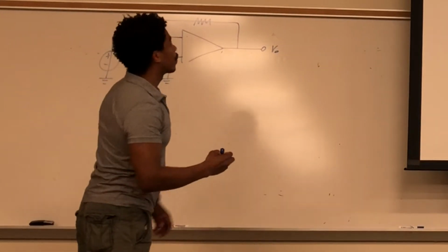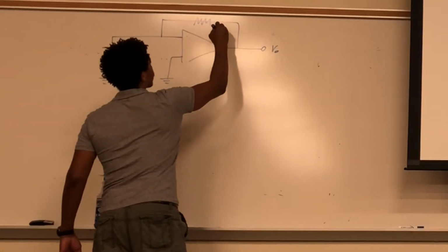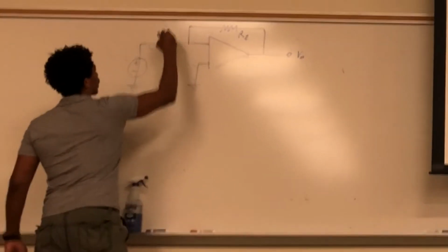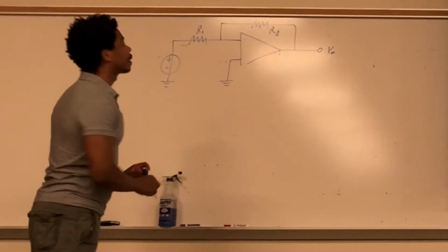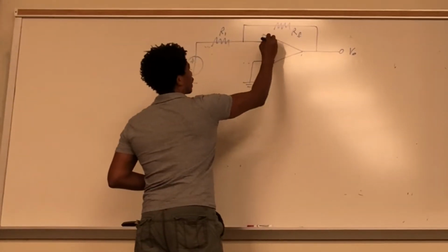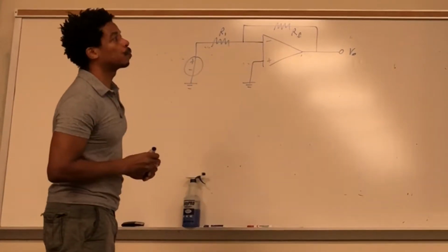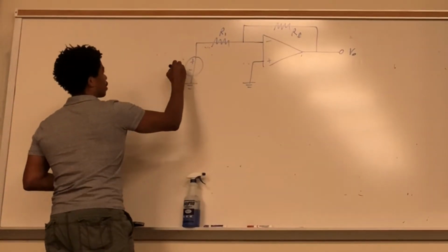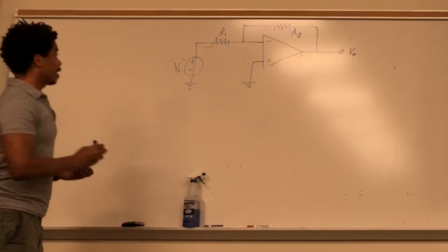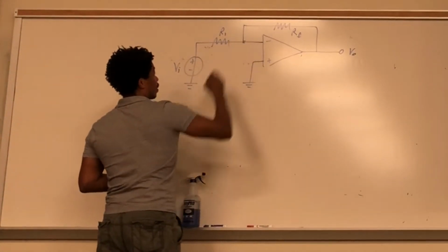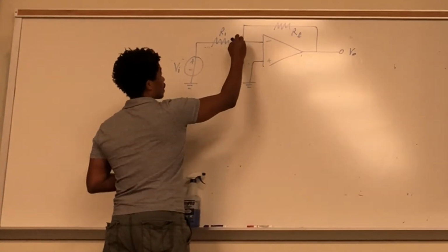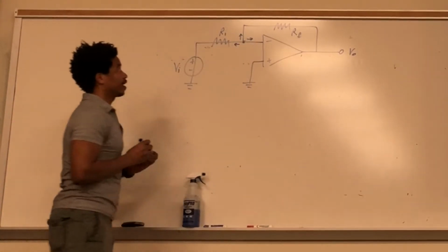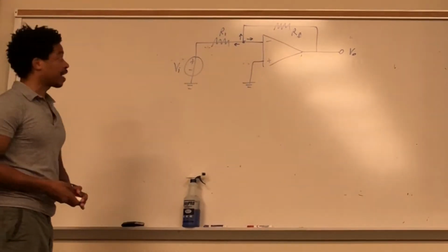Okay, so we have this feedback resistance right here, and I forgot about this resistor. Here goes R1 right here, plus and minus. Okay, that's all we have. So let's do KCL right here. We have these currents. Let's define them leaving that node as being positive.